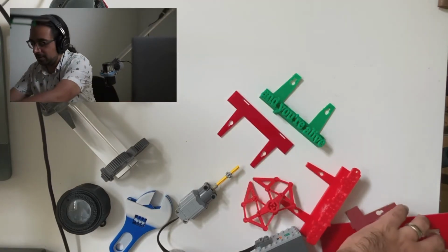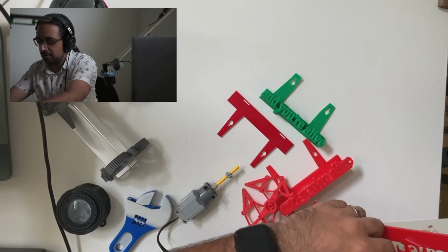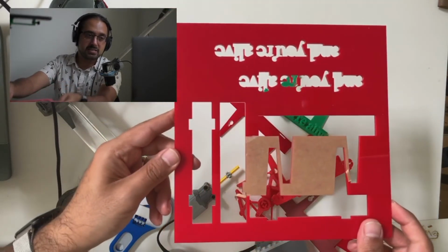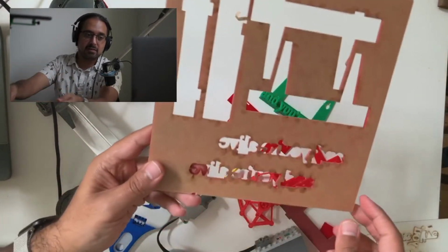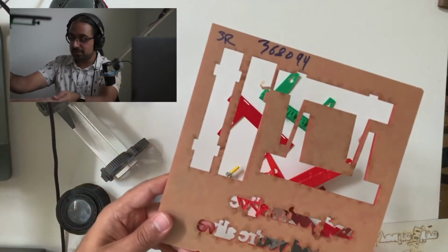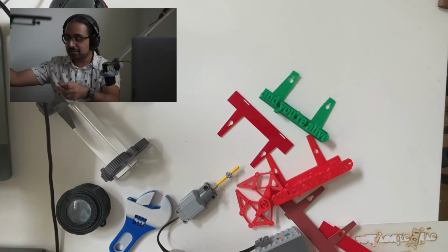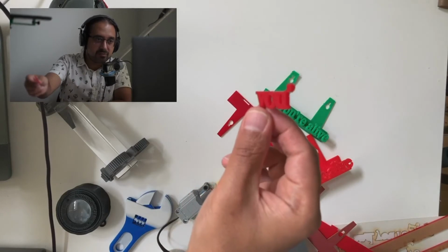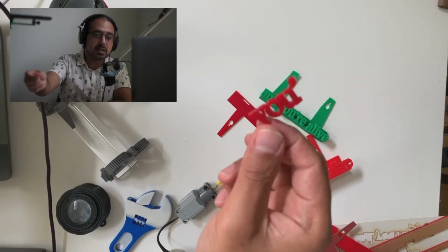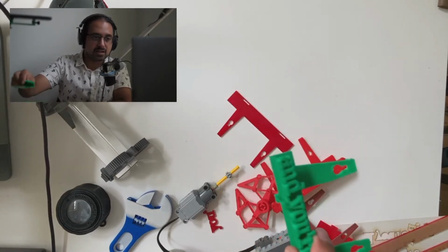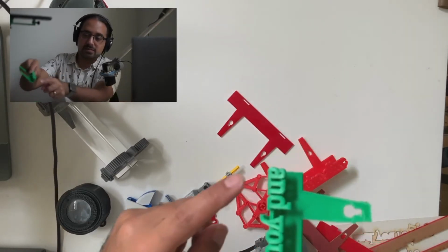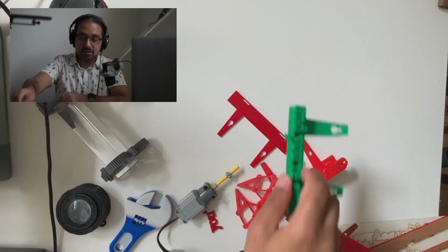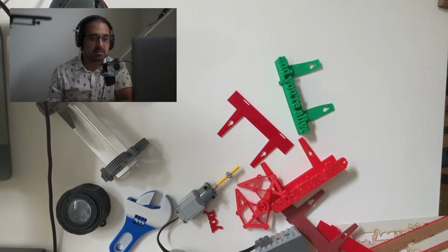So let me see if I can grab this just here, but I'll show you what the laser cutouts look like. What had happened was that we basically laid out the pieces that we wanted to print out on one of these sheets, and then you effectively just punch these out and then glue them together. They're cut by lasers, and because they are laser cut, they're a little bit more precise than you'd get with a 3D printer. As you can see here, there's fairly fine edges on this. But what you don't get is the kind of nice rounding on the lettering that you get with 3D printing, right? So you can see here that we've got these nice rounded beveled edges on the letters. And that would have been extremely difficult to achieve with any other technique.